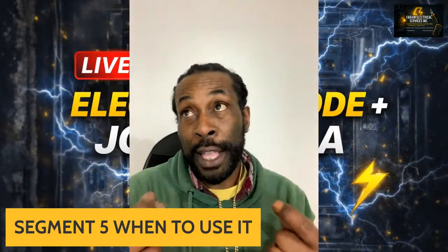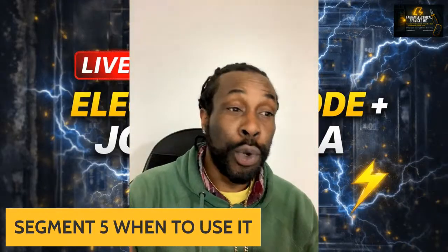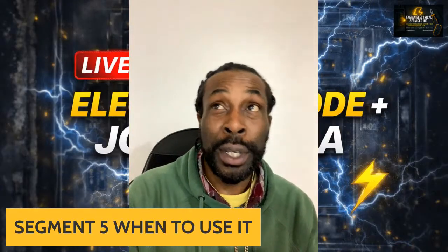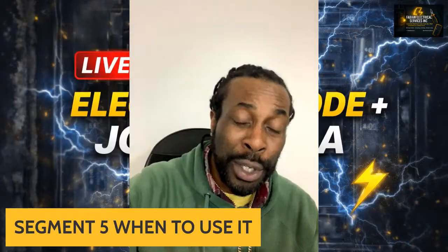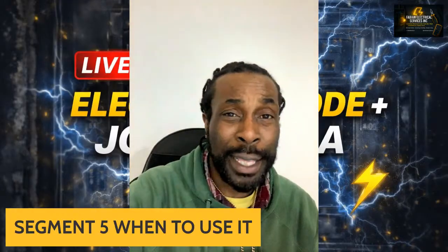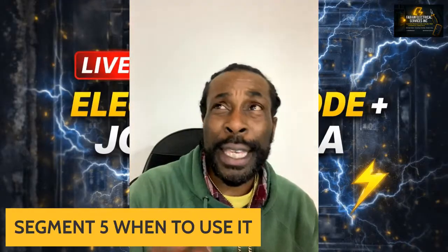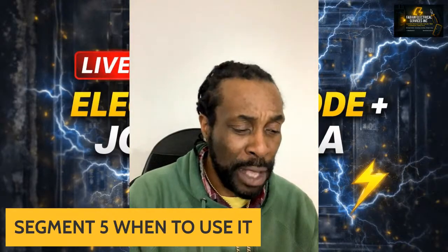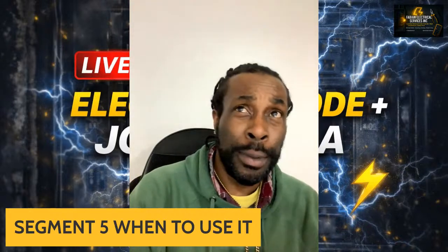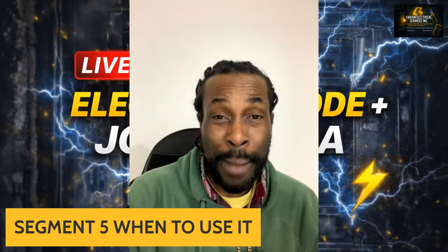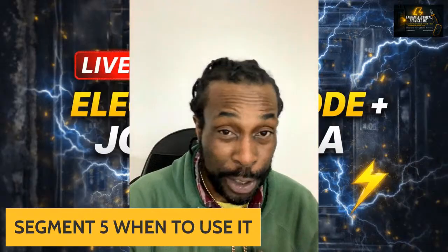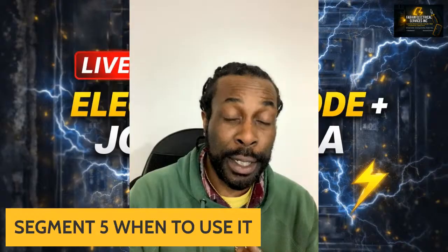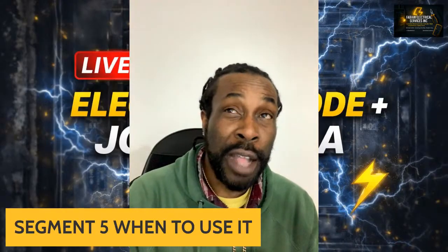So you'll find a lot of times you will go into a receptacle, and if you made connections, sometimes you plug your light into the outlet and the light starts to flicker and so on. That's a wiring problem. That is a loose connection, possibly on the receptacle itself in the box. The backstabbing does that a lot of times.